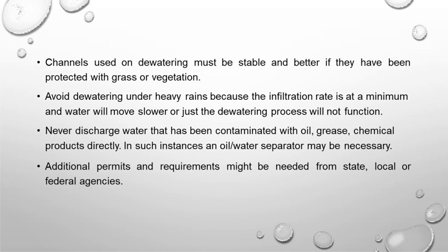Okay, so how does it work? Before starting the pump, priming is done. Priming is nothing but water being filled into the suction pipe, the casing and a portion of the delivery pipe up to the delivery valve. This is done for the removal of air. With the presence of air, it is not possible to create pressure, because the pressure generated by the impeller is directly proportional to the density of the liquid to be handled. That's why we need to remove the air from the impeller, and so we do priming, that is, filling water through the funnel.